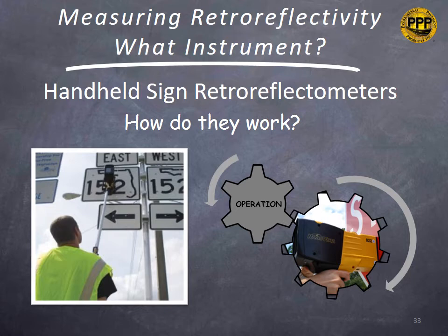So what about mobile sign retroreflectivity? Mobile retroreflectivity of signs is being worked on, but cannot be achieved using the current ASTM standards, as they require entrance angles that actually do not exist in the field. Even if we change the standard, we will have to deal with the variance in sign placement, types, sizes, colors, and shapes. It will be difficult to get an accurate measurement. The first generations of these will be best used to determine which signs need handheld retroreflectometers to be used on them.